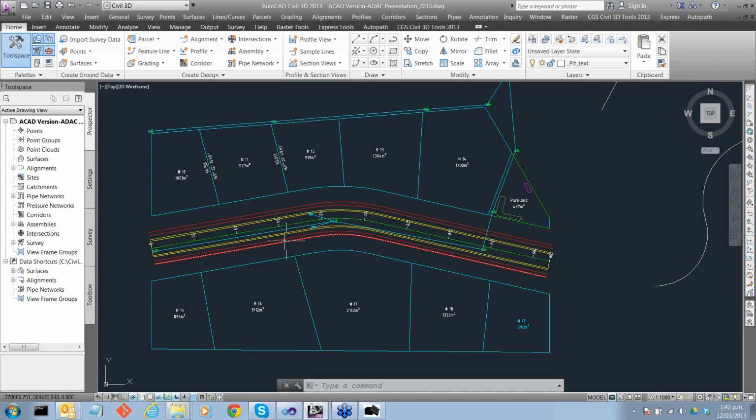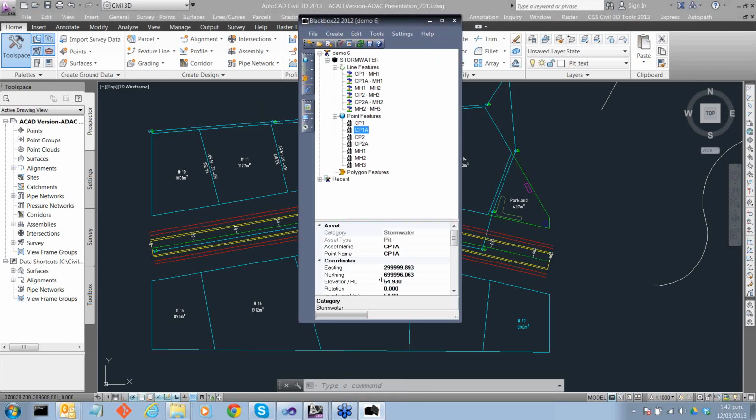And so now all those features have been returned back to my screen because basically I've closed that editable copy drawing. So now I'm back to the original. And that's basically what it is to layer mapping. It's just as simple as that. It's a one-off thing that you need to do. The settings are saved, and you continue to use them.